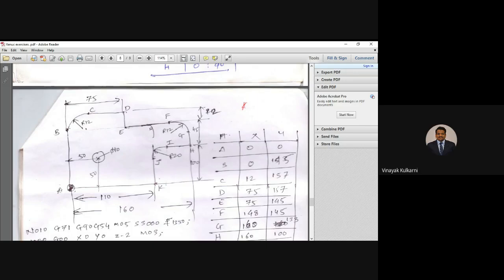Now both these curves were clockwise direction. Now this is something anti-clockwise direction. So again here I will draw x and y axis. This is negative x and negative y. So from here again what I'll do, my r value is going to lie somewhere here. So I is 0, J will be minus 20, but my G02 will not hold good here because G02 is clockwise.